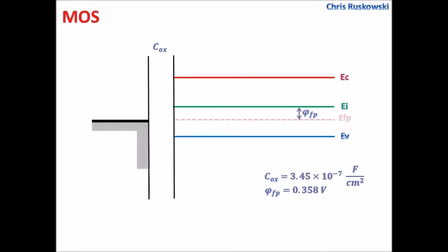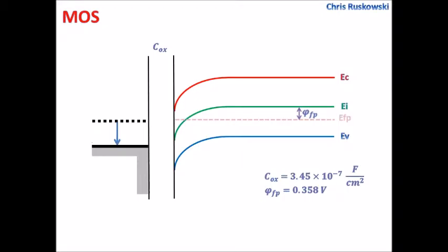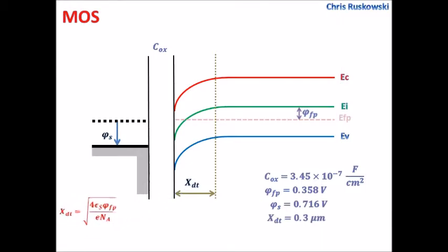As you can see so far, here are some of the values that popped up on the screen. I do want to pay attention to that when we apply a positive voltage to the gate, we're going to bring electrons to the surface, which will cause band bending. Here, we calculate the threshold voltage as twice the Fermi level. Also, at threshold voltage we're going to have maximum depletion width, which is calculated with this formula, as shown off to the side.